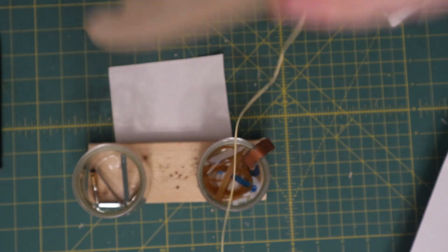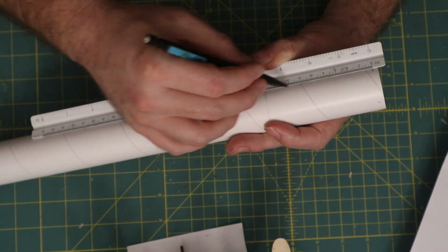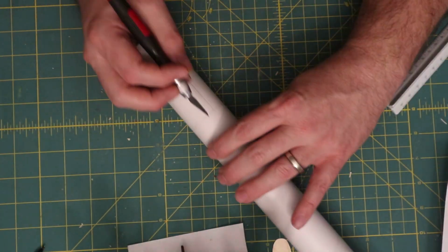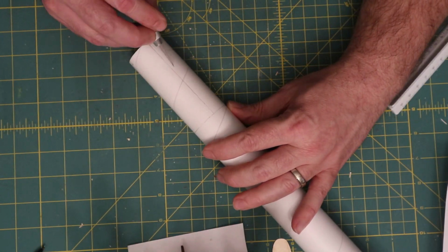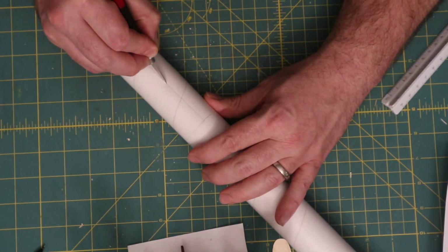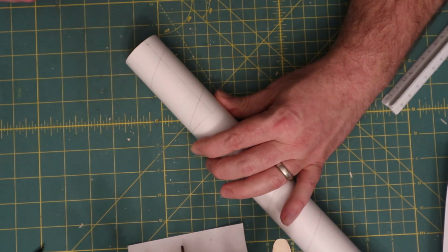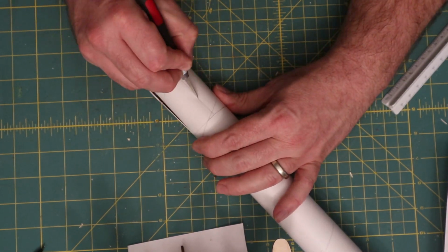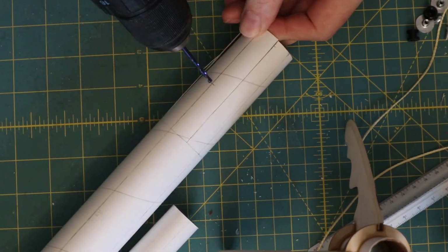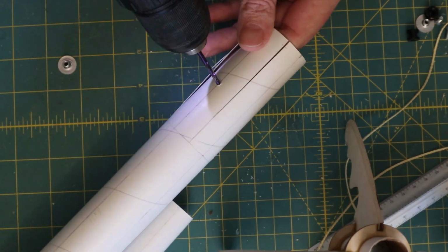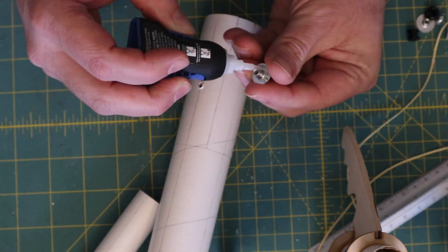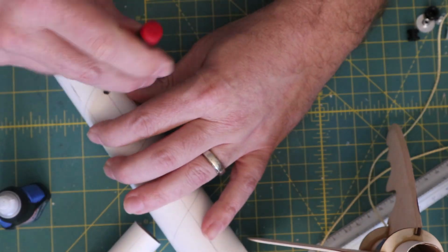One thing you'll see here is I do just slit the airframe. That didn't end up working out, so you'll see later off camera I came back with a file and expanded those out and then cut little notches in the bottom to help with assembly. Next, we're going to drill a hole out for the rail button mount and then come in with some CA glue and glue that into place.